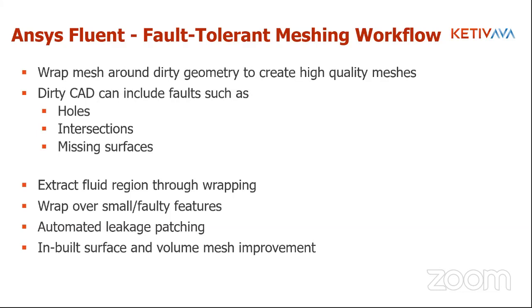In some cases, it is easy because the geometry is simple enough, but there are other cases wherein the geometry gets complicated, there are minute features, you have to go into each nook and cranny, and it becomes tedious. You might not have the time or the personnel to go through these steps again and again. In that case, wouldn't it be great if you could completely bypass this step and directly go from an unclean geometry to a CFD mesh? Well, fault-tolerant meshing allows you to do exactly that, going from a dirty CAD geometry to a CFD mesh and generating a high-quality, efficient mesh while doing that.